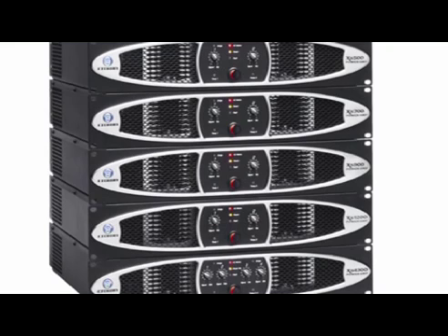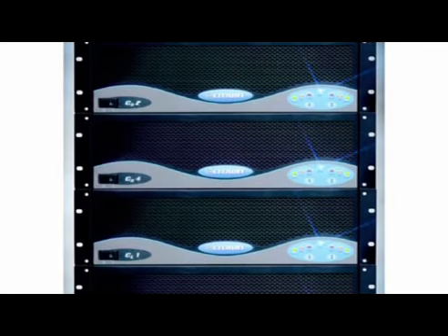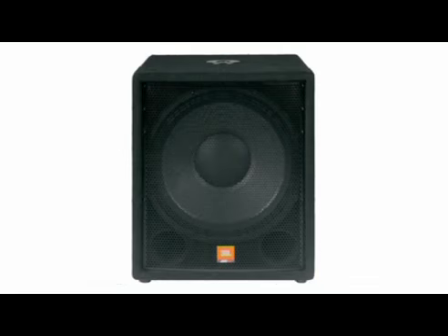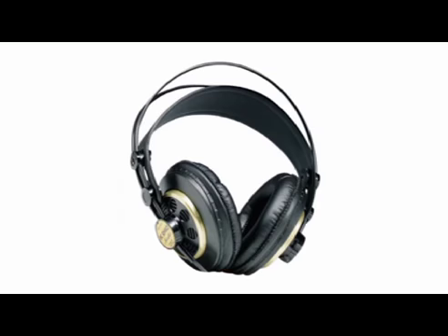Surprisingly, you're more likely to blow up loudspeakers with an underpowered amplifier than an overpowered one, because when an underpowered amp goes into clipping, it produces extremely harmful high frequencies, which can send even the best tweeters into oblivion. You really need dedicated PA speakers for live work. They're built to take knocks and all sorts of abuse that would instantly pulverize domestic loudspeakers. There are all sorts, and you still need to treat them, as well as your ears, with some respect. When you're choosing headphones, avoid open-backed ones and make sure they're comfortable.